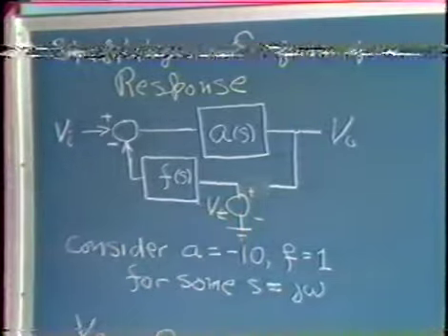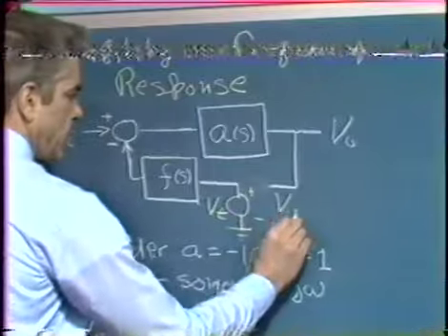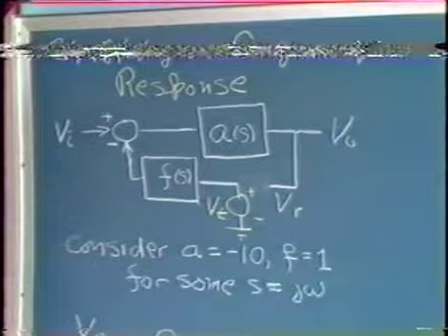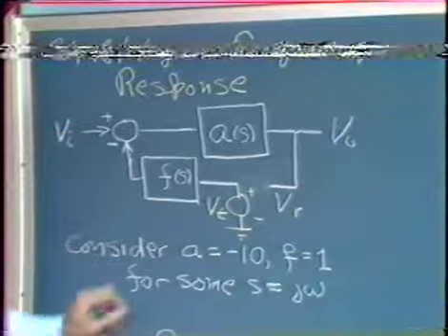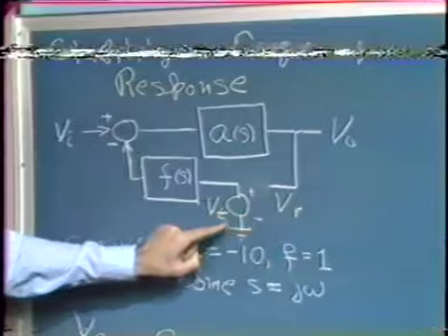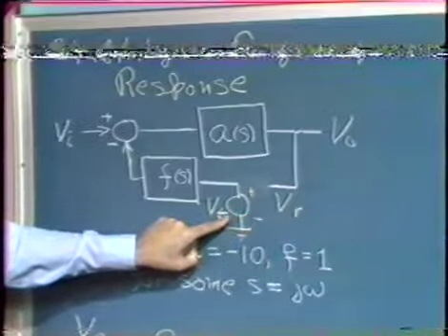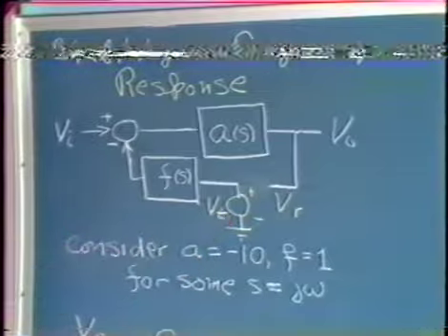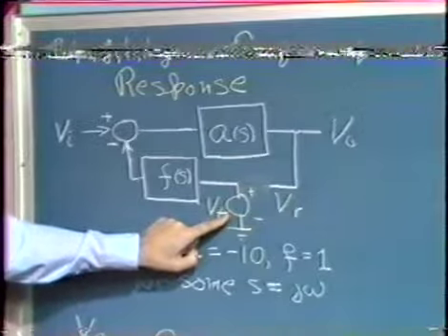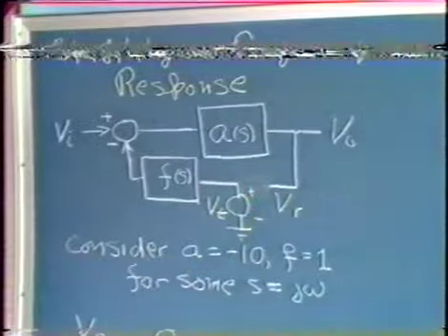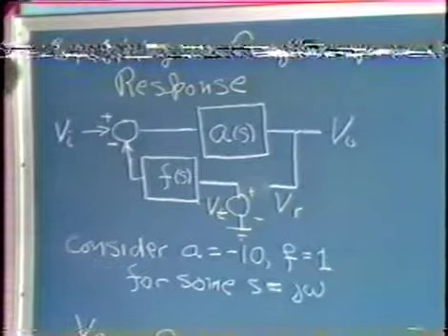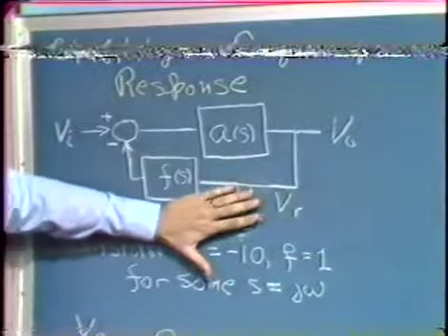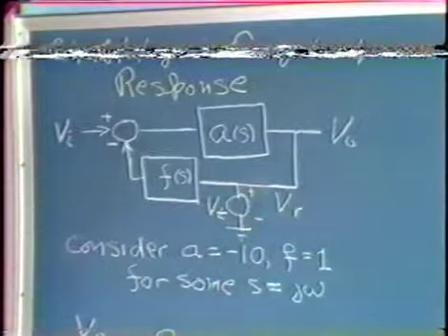And look at the signal that the loop returns, possibly V sub r. And we found out that for certain systems, in the absence of an input, we'd be able to get V sub r to be identically equal to V sub t under sinusoidal steady-state conditions for some frequency of excitation. When that happens, we said, well, we could then imagine oscillation because we'd be able to reclose the loop, take away our generator, and the system would continue to oscillate forever.